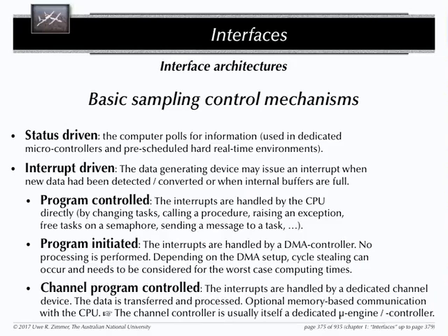So you program your AD converter to trigger an interrupt, which is ultimately not going to your CPU, but your interrupt controller reroutes this to a DMA controller. The DMA controller will be activated. The DMA controller grabs information from your AD converter and stores it somewhere in memory.